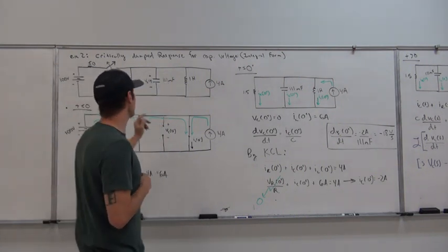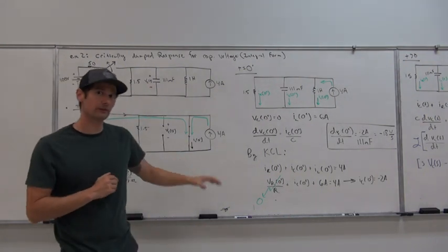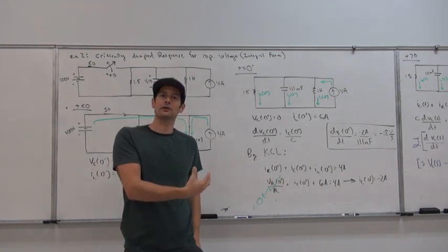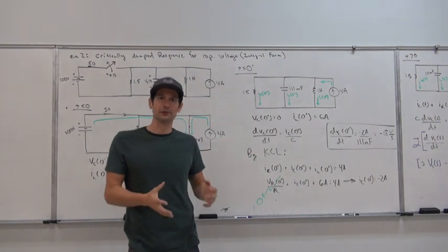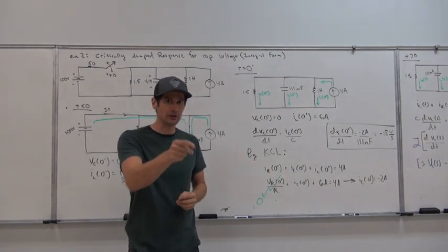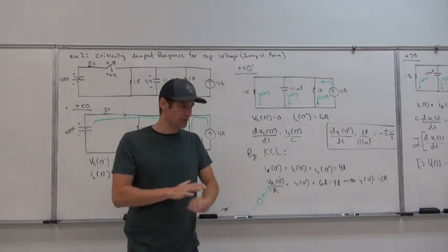Now, for this problem, we wanted to find the capacitor voltage, and like I said in the prior video, when we have the KCL equation, we know because they're parallel elements that they're all going to have the same voltage. So once we expand that KCL equation by the current-voltage characteristics, everything is put in terms of voltage immediately.